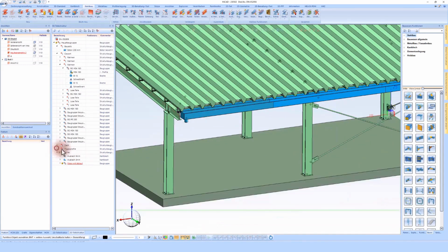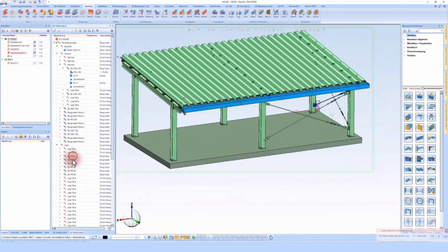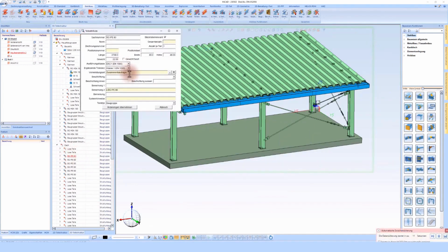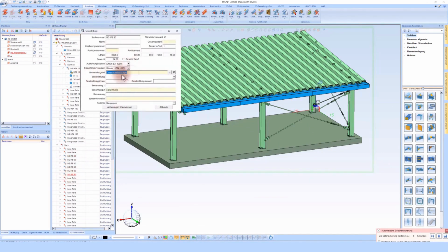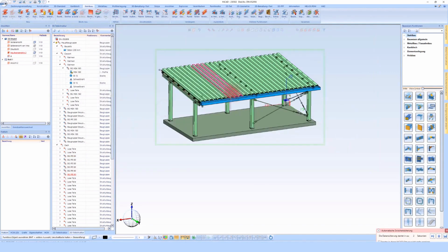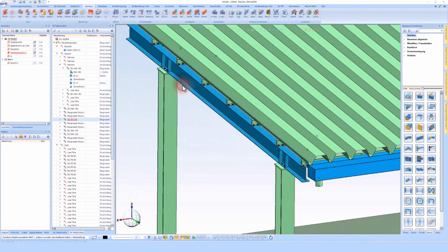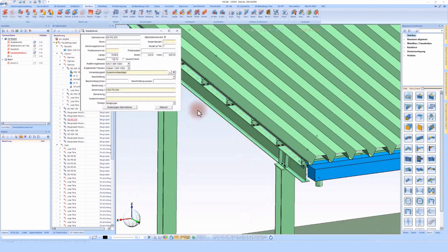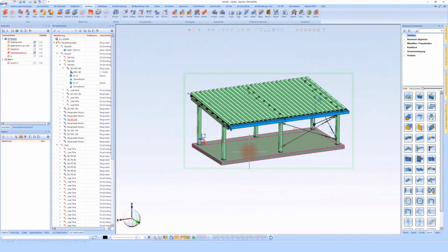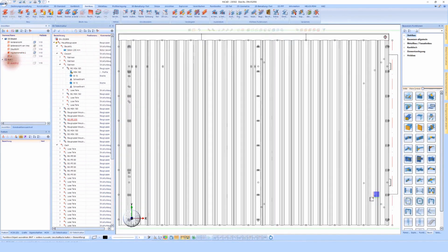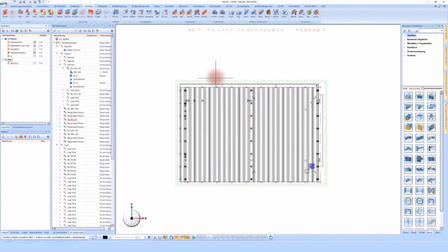So next I will take a look at the structure, and I can, for example, also check the beams to see if they have these usage types. In this case, you can see that they have the usage type assembled beam, which usually produces very nice drawings in beam constructions. So that means my model is finished in this regard, and now I first switch to my sheet area. HiCAD has first gone to the top view.